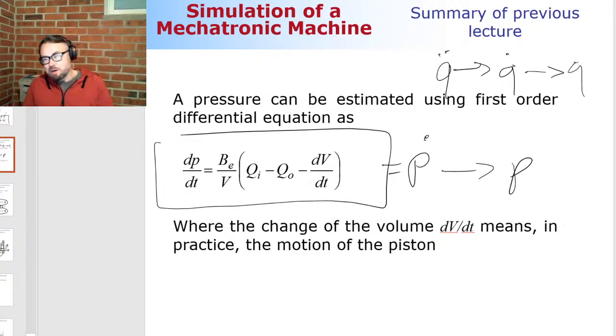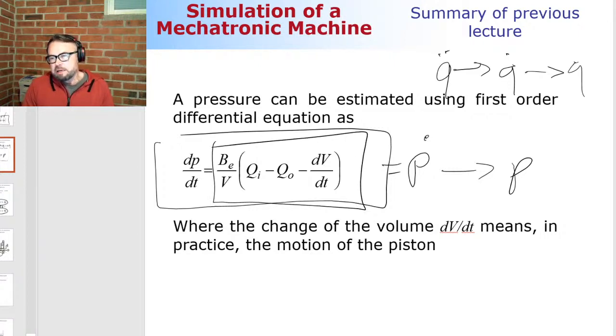Okay, back to hydraulics. What do we have in this first order differential equation? The components here are the effective bulk modulus, which is a description of flexibility. Soon there will be a question about what lumped fluid theory ignores. One of the options is flexibility. It's not ignoring that, because flexibility, as you can see, is in this equation. Volume size is here. The volume can change its size, which is particularly the case in hydraulic cylinders, and that is accounted for as well.